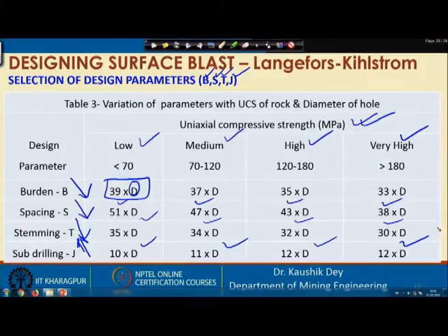We have to design for a lesser burden, lesser spacing, lesser stemming if the rock strength is increasing. That is as per our requirement, because the explosive charge quantity required is more for the stronger rock, and this lesser burden, spacing and stemming basically ensure that the charge per unit volume of rock will be more if the rock strength is high.